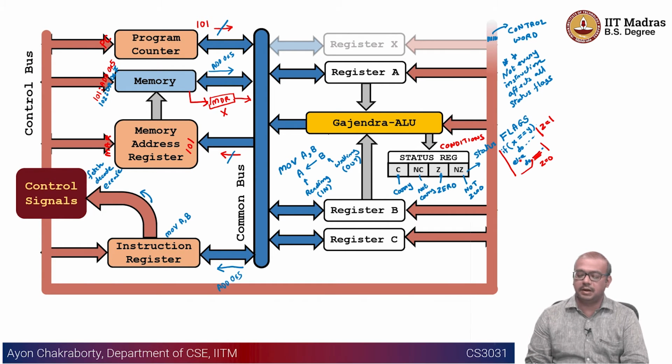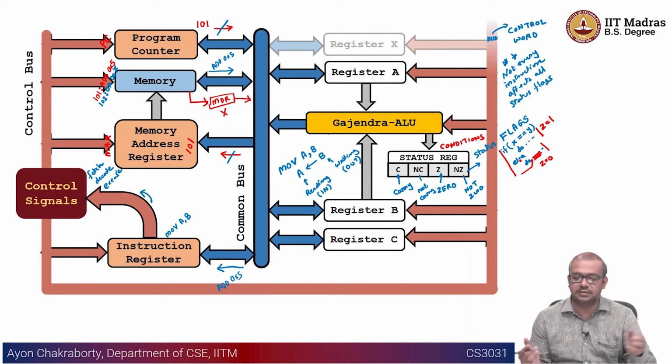Okay, and recently you have the RISC-V architecture, which is an open standard for the ISA or instruction set architecture. You have to follow a certain mandated set of instructions or a certain pattern. They basically tell you the list of instructions that need to be supported and the way the instructions are formatted, right? And as long as your microarchitecture implementation of that ISA is compliant, you make a RISC-V compliant CPU.